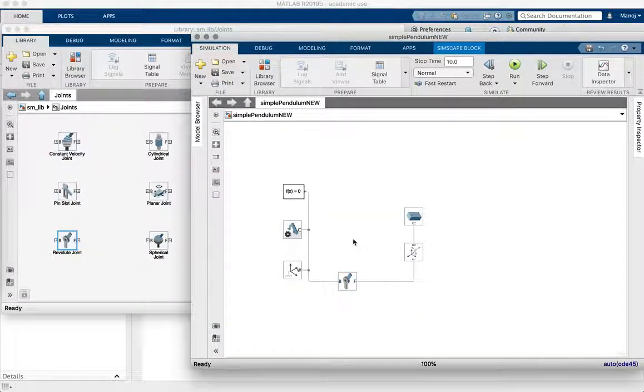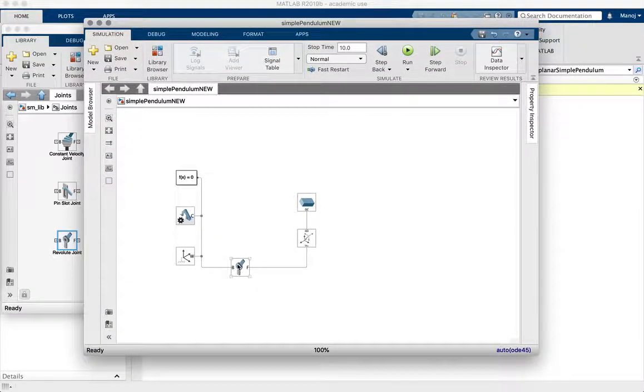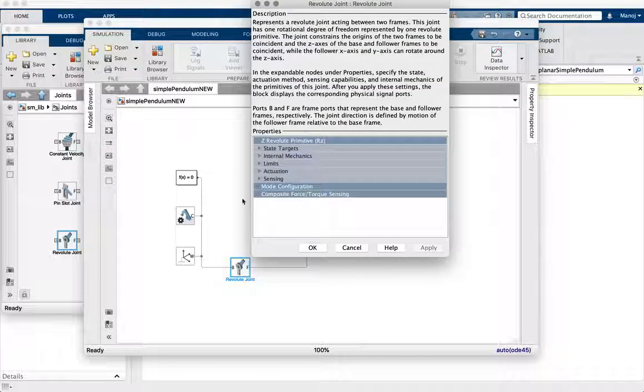So it took a while. It takes a few minutes to create this animation or simulation. Notice that we didn't do a couple of things that we were supposed to do for doing a simulation like this. We didn't yet define initial conditions for the system. How do we do that? It looks like it just assumes some default initial conditions. To actually do that, the initial conditions are specified using the joints.